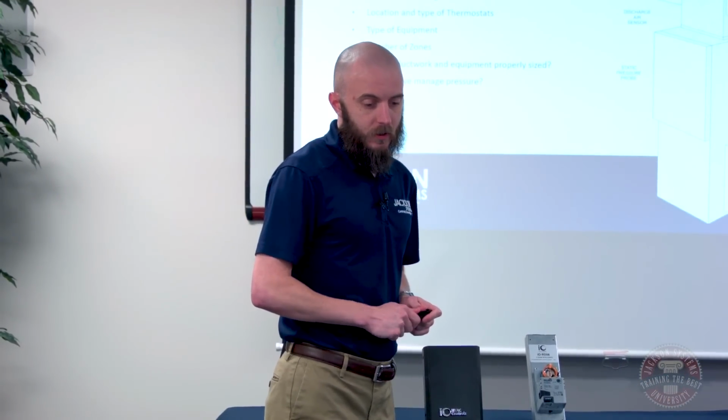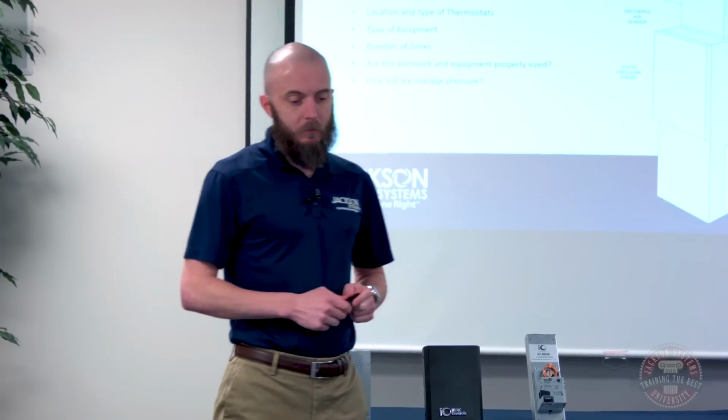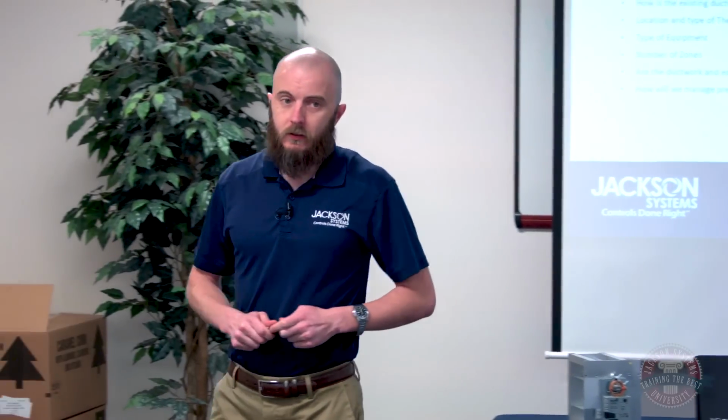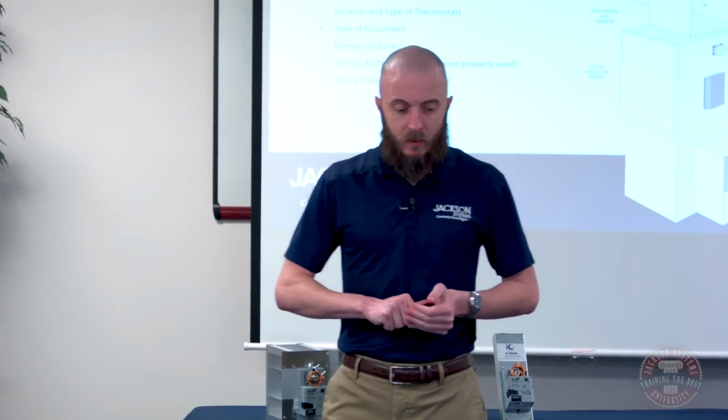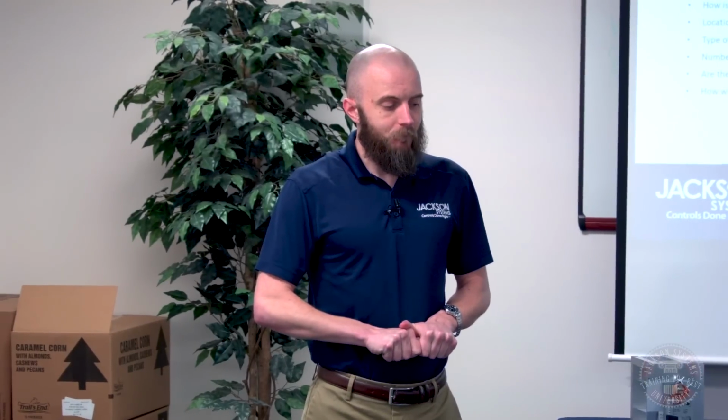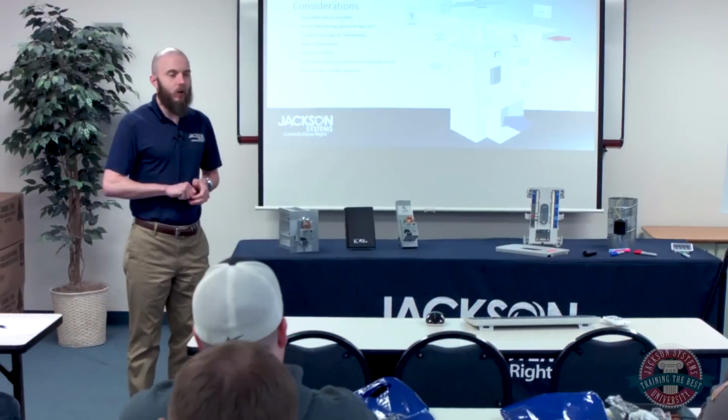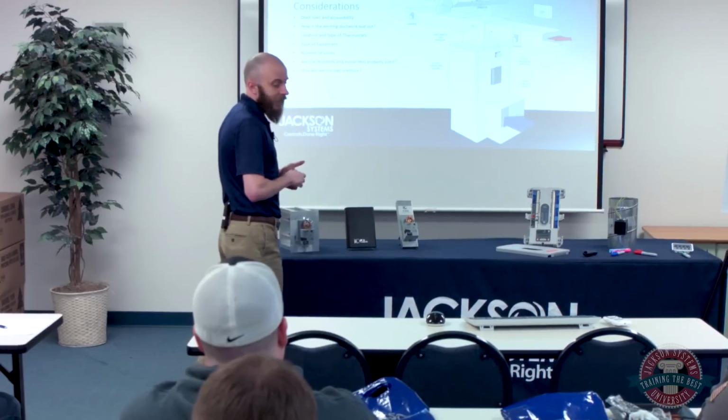So this next question here is, is the ductwork and equipment properly sized? This is kind of a big one. So we recommend never ever assuming that the ductwork is correct and the equipment is sized properly when you go in to do a zoning job. It can be crucial. Probably more often than not, the ductwork is probably not sized properly.